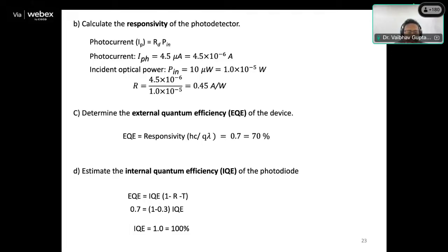When I say internal quantum efficiency, I mean how many electrons there are as compared to the absorbed photons, not the incident photons. And this is theoretically 100%, but in practice, some of the electron-hole pairs will get recombined. They will not come out into the circuit and will not contribute to the current, or maybe during the diffusion process, they will decay in terms of heat.